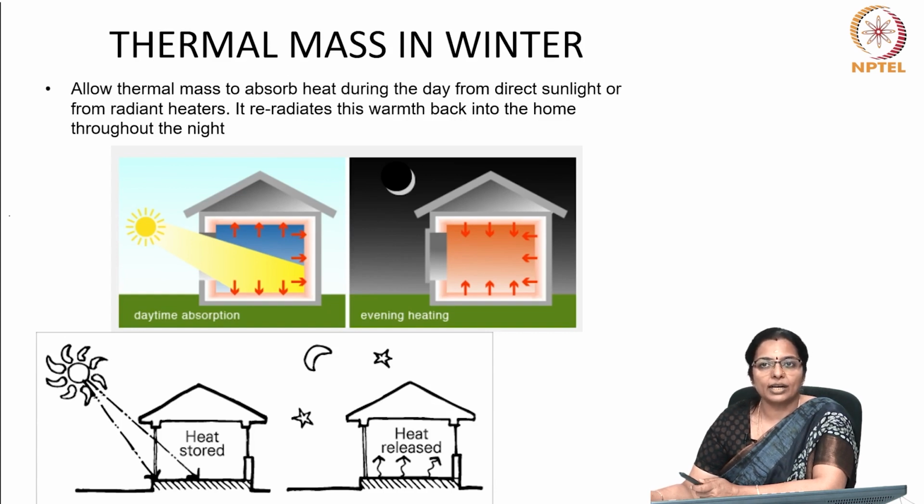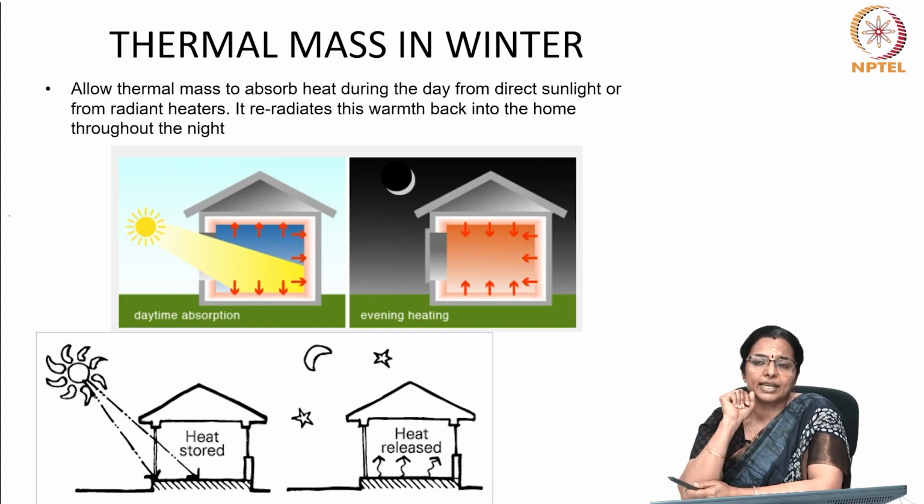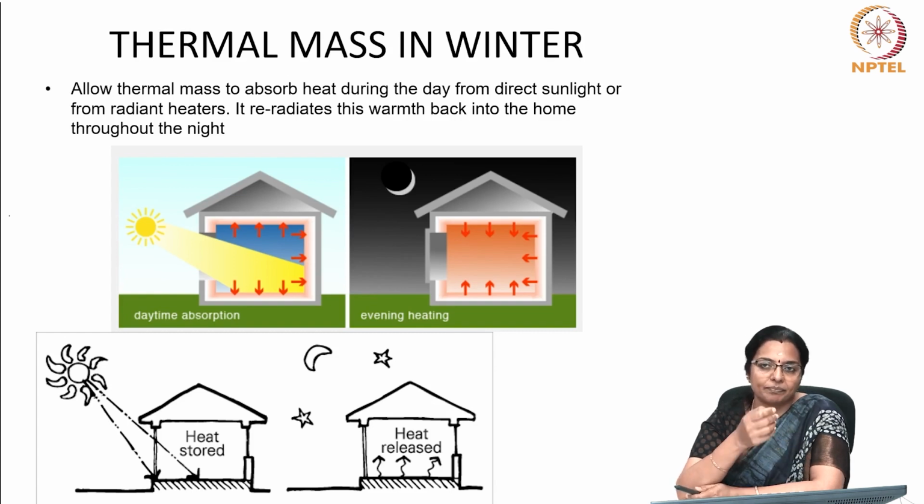In warm or hot climates where there is significant temperature variation between day and night, also called diurnal variation, heat is absorbed during the day and then released in the evening, when the excess can be either flushed out through nocturnal air ventilation, or used to heat the space as the outside temperature drops. The entire process can thus be repeated the next day.